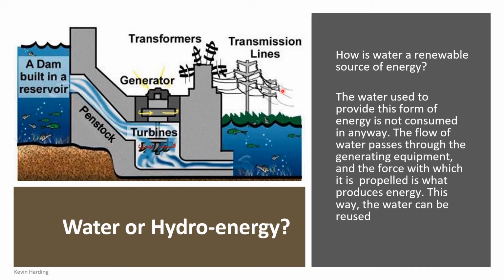There are some systems of this. We have hydropower as an emergency backup supply. So what will happen is that during peak demand times, during the mornings and the evenings, Eskom, or the power supplier rather, will open up the dam wall. We will let the water go down to supply extra power to the community. Then during the quieter times, this water is pumped back up to the dam, ready for use at a later time. This is used in Cape Town, where Cape Town's got nuclear power. Nuclear power, we can't switch it on and off, it's on all the time. So that surplus energy from Koeberg and the nuclear power plants will pump this water back up to the dam for peak times.